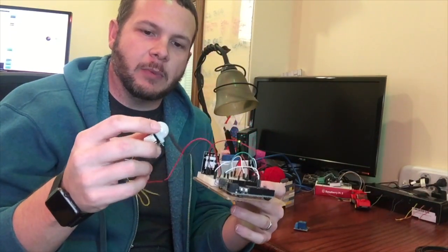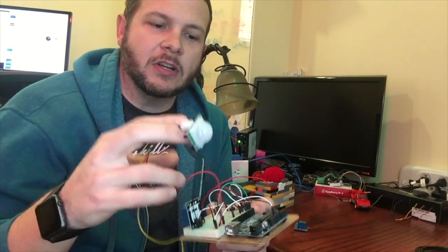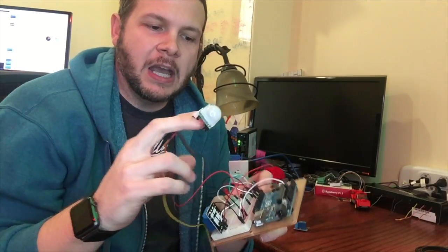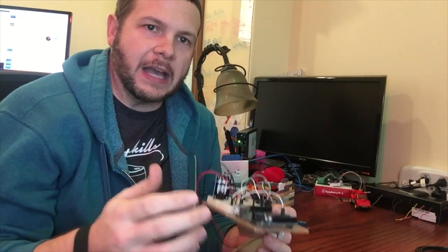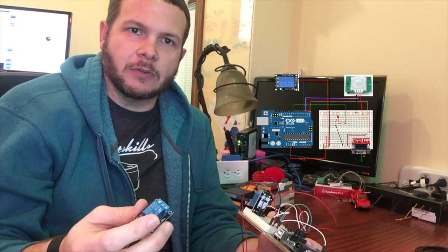Now here is the mock-up that was used originally for the Giant Ball of String, and we can see this is just a very cheap $10 motion sensor integrated with an Arduino microcontroller, the open source microcontroller. By monitoring the activity through the motion sensor, we can then control the activity of the lights using very simple relays like this that can turn on and off the lights. Other options are really as big as the imagination for a consumer for this.